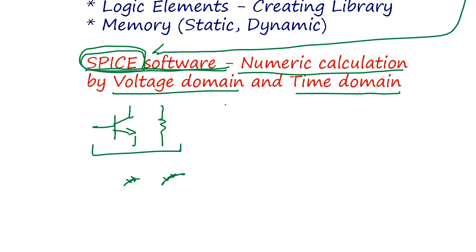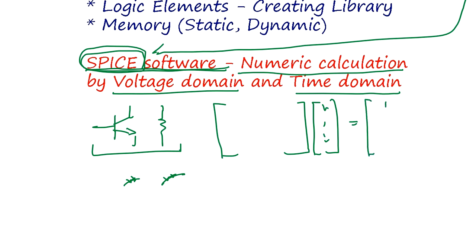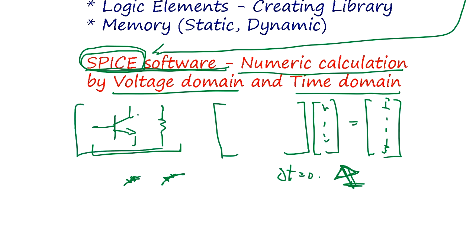It's calculated by computer as a linear model. So this amounts to solving a matrix calculation, and it has voltage and current and time step. So each time step it calculates the voltage and current using Kirchhoff's theory. Kirchhoff's theory is basically using a linear matrix calculation. You solve it at very tiny steps, step by step, and calculate the non-linear circuit. So that's what the SPICE software is. It's very well established, and everybody uses it for the design of linear circuits.